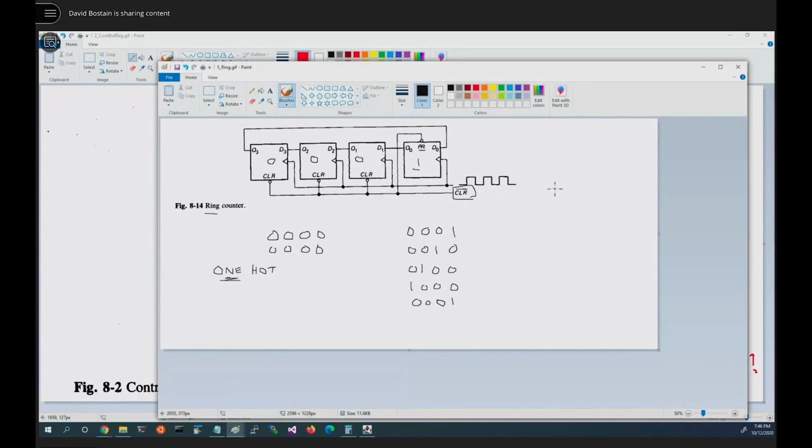All right. So basically what we're doing over here, we got a button, right? And we've seen it before. It has clear in one, I don't remember which way they drew it, but it had clear in one position and it had start in the other. Probably had it backwards to what I just drew. So the signal we're actually working with is clear. So when clear goes high, what does not clear do? Well, not clear was high, it goes low. And we need it to go low to push that button. So we have to hook not clear to this signal, because if we hooked clear to it, clear would always be holding it low until we said clear. That make sense? Yep. Okay, good.